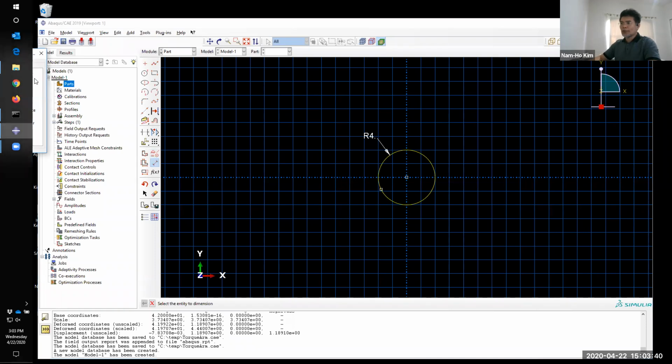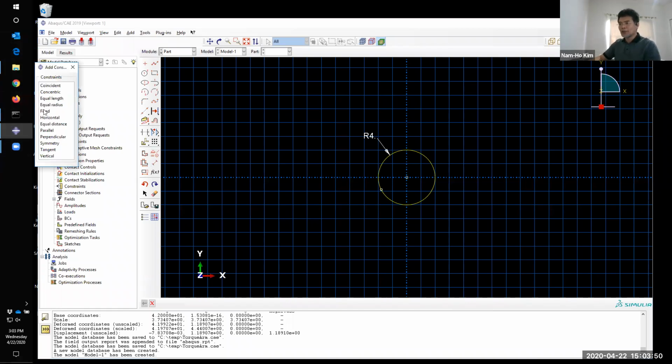So if you can open the constraint here. Not to move it, okay. All right, there. So there are many different constraints, out of which I will choose the fix, meaning I will choose a point and then we'll fix the point. So if I choose this point, which is the center of the circle, okay, then now you see that your circle becomes a green circle, because it means it's fully constrained. It is not allowed to move horizontally, vertically, and the radius is fixed. So it's fully constrained, and now the circle becomes a green line.